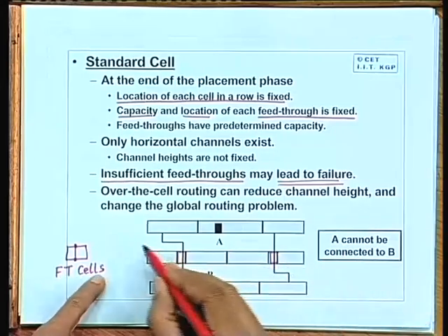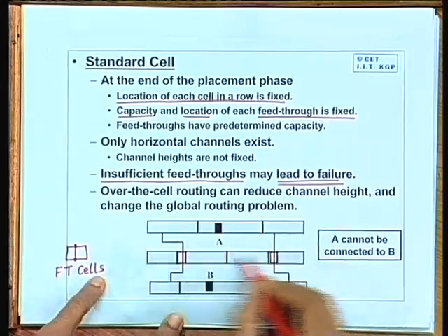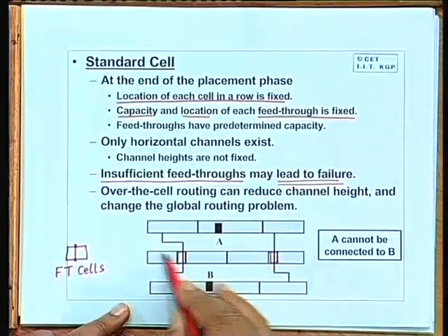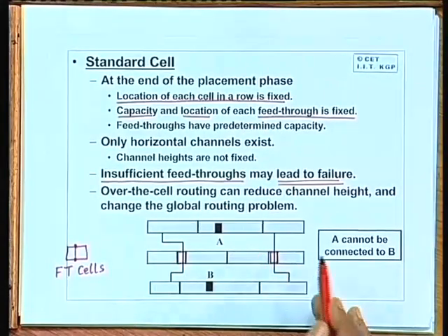So, you will have to undo all the routing you have done and then insert it and then redo it. Because if you shift a part of it, it will also carry all the wires along with it. The topology of the interconnection may become very inefficient if you just drag it like that. So, you can insert, but you will have to redo the routing of the corresponding channel after you do that.